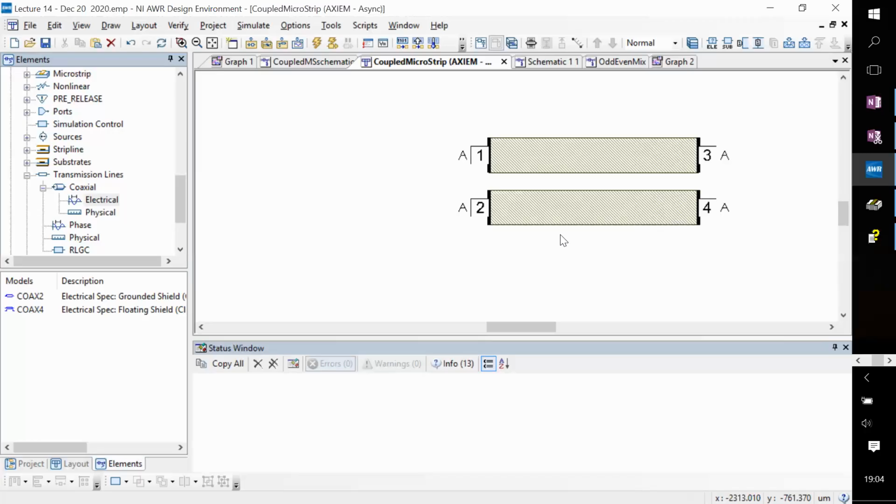Okay, and it is also matched to 50 ohms on all the ports. So which means that if all the ports are terminated by 50 ohms, then that fourth port will also not show any reflection. And again, remember that many of these properties are often idealized properties and will typically only be satisfied for one frequency perfectly, but it will be satisfied for a reasonable number of frequencies over which it is designed to work. And that depends on the design.